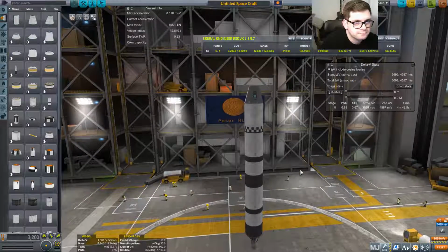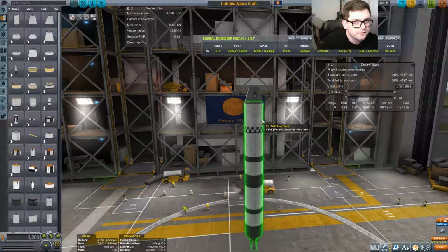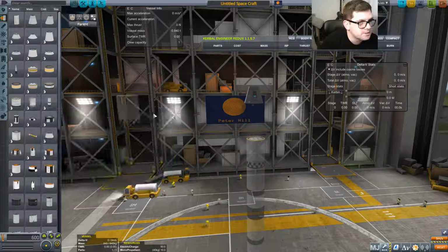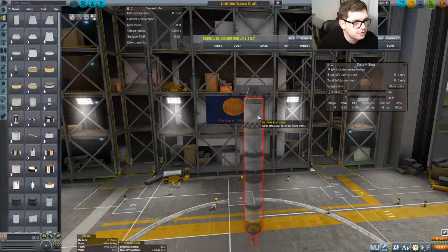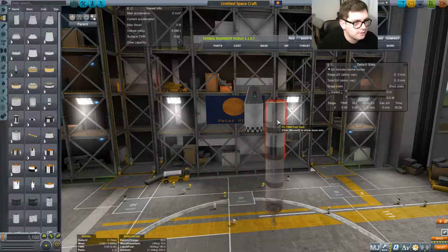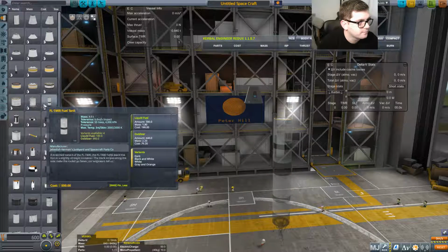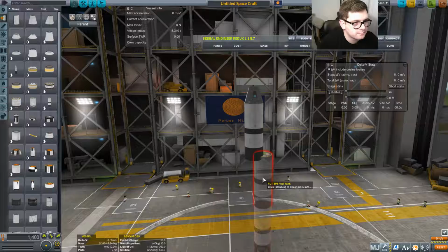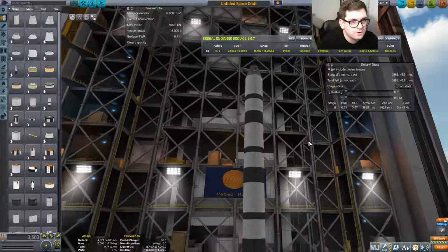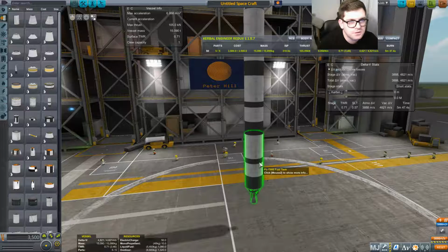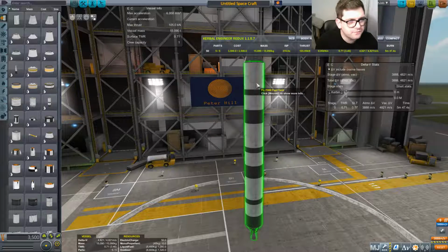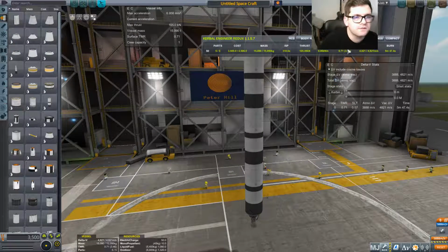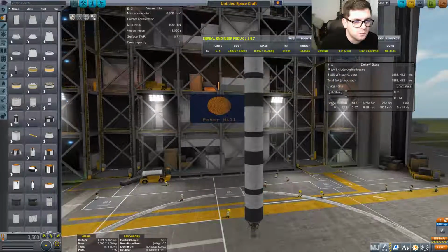So we're now at 4,587. The problem you're going to get now is diminishing returns. Okay, so let's maybe double the size of that, because these are double the size of that one. Let's put another one of these on, okay. So you've only increased that by, so one of these was 2,500. This went up to 4,200, but then this one only actually added 500 meters per second. Now the reason for that is that our TWR has dropped below 0.71.